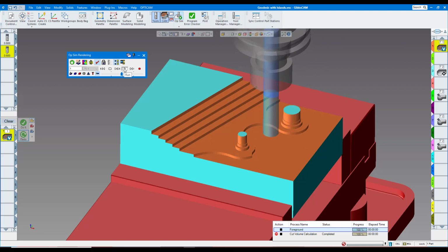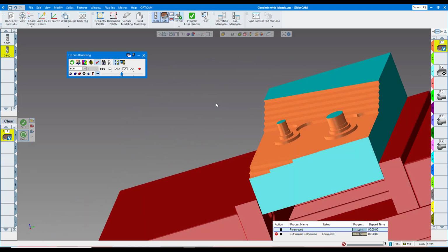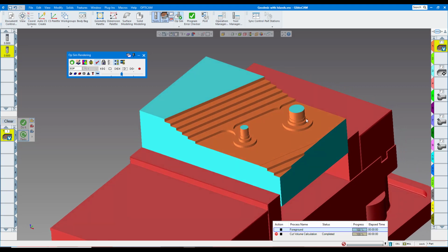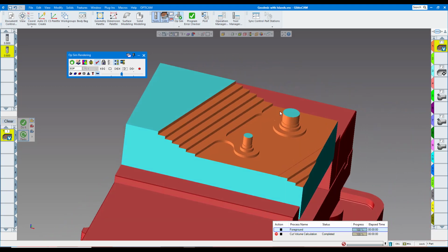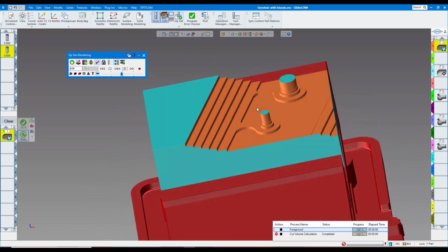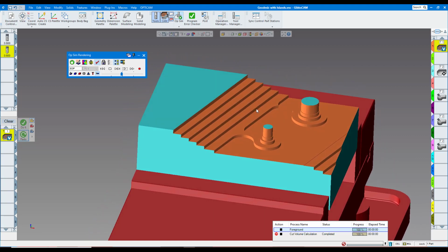you'll see now that I have a good tool path for the ball end mill to come in and take a finish pass. Ideally, I'd do probably a semi-finish with a ball end mill then a finish, but once you see the ball end mill, you'll understand that you could just change the step over and how much stock you're going to leave for the final pass.